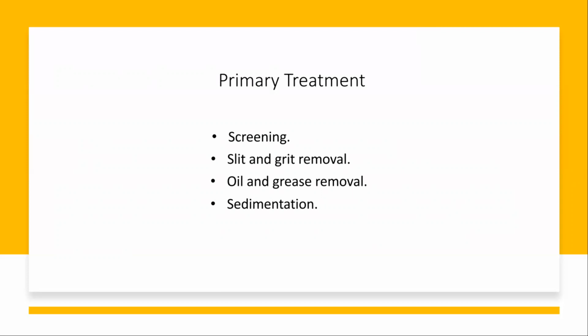And the next process is the sedimentation process. This is used to remove the fine suspended impurities. The particles which do not settle down by gravity can be coagulated by the addition of coagulants like alum, ferrous sulfate, etc. And the sediment particles are filtered off.